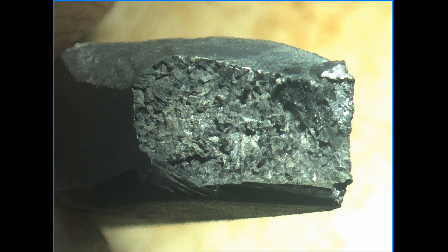My point, you don't sit in one spot with a TIG welding gun. You can't just sit in one spot and get it hot and get it hot and get it hot. You're causing trouble. You're causing deficiencies in strength as well. You'll start the annealing effects of too much heat. Not only that, we start to pick up oxygen. The material, that is aluminum, is very finicky that way.